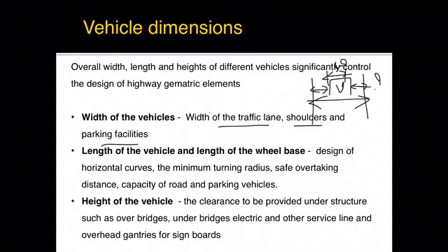And also whenever you take up electric lines or any cable lines, there should be sufficient clearance between your vehicles and those lines. So it is essential to consider the maximum height of vehicles allowed. And also the overhead gantry signboards, the signboards taken across the roads: the height at which you provide them is decided based upon the maximum height of the vehicle expected on that particular road.